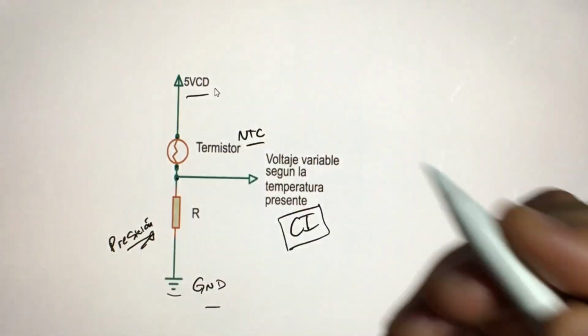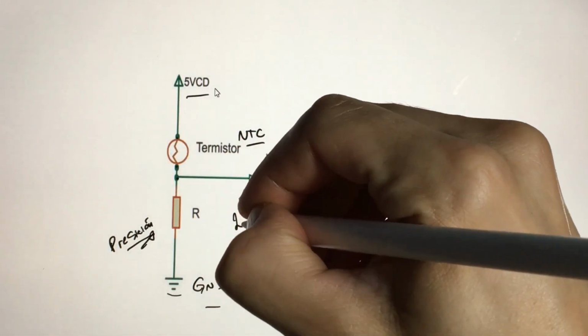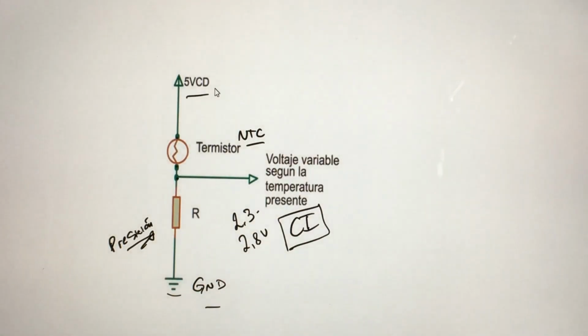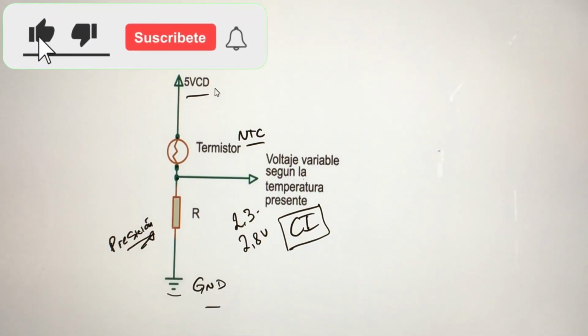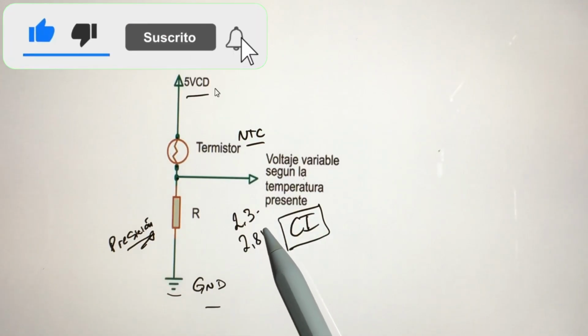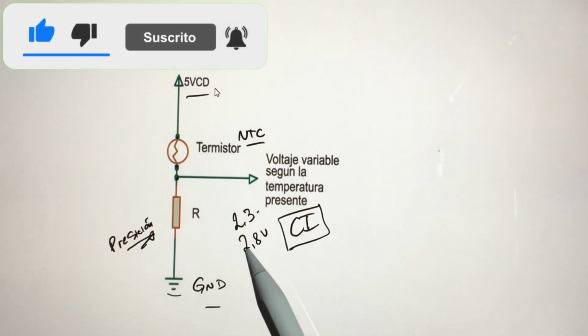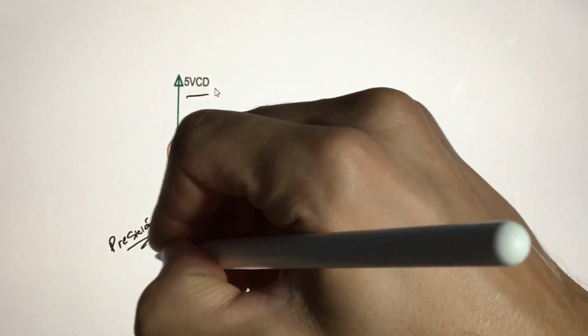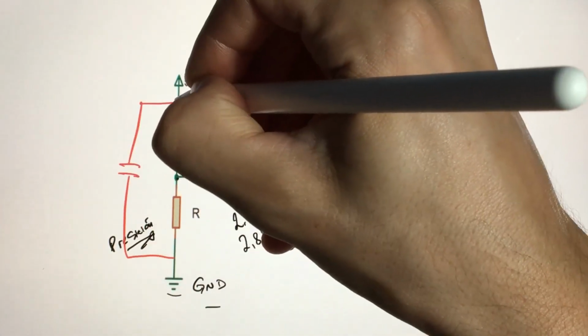If we inject 5 volts into the sensor, approximately 2.3 to 2.8 volts will be injected into that integrated circuit, and through this variation, it understands what temperature it is. Of course, it understands it in a much more accurate way, 2.340, 2.565, we talk in the range of millivolts, so the microprocessor understands it. Something that is not drawn in this diagram, which you will generally find, is a capacitor that is placed between the negative and the positive.